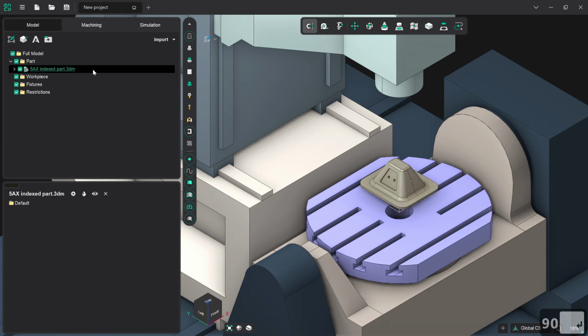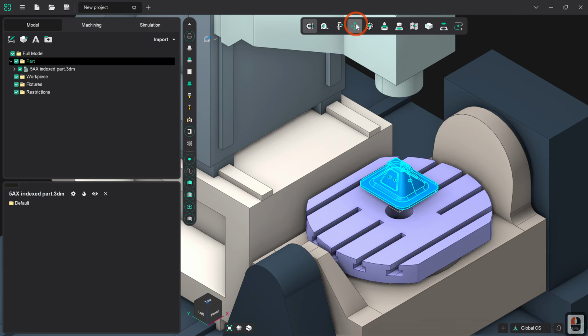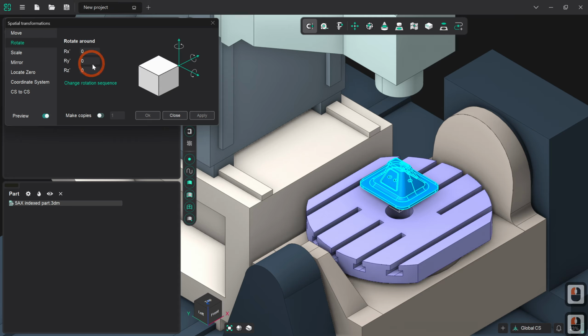And this is why you always want to test something first. I typed in 90 and then return, and the window closed. Always check what you're doing, unless you really want to get tied up with having to undo things or go back or restart the entire process. It's just good practice more than anything. We can, however, always reopen the spatial transformations window, and provided we remember the number and the axis that we dealt with, and we haven't gotten ourselves all tied up and confused, you can always type in -90 to get back to where you were in this instance.